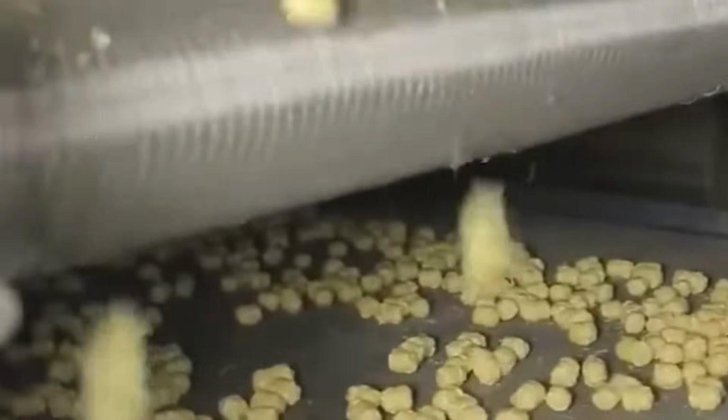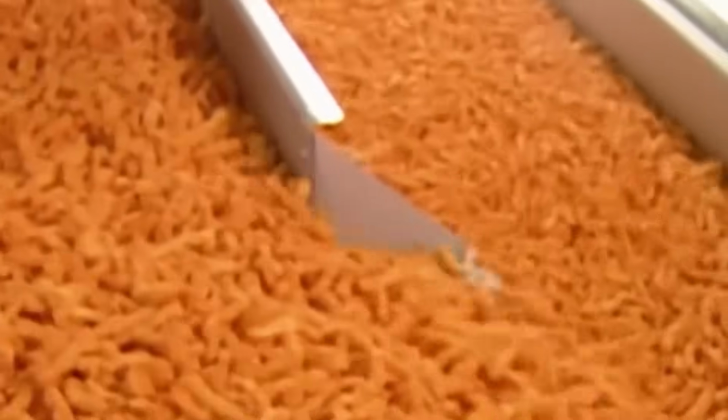The cornmeal is sifted through mesh screens to remove foreign particles, then passed through a dehumidifying chamber to achieve a standardized moisture content between 10.5 and 11.5% before entering the preconditioner. In the preconditioning chamber, dry cornmeal is mixed with water and steam under tightly regulated parameters. The purpose of preconditioning is to hydrate the meal to a target range of 18 to 20% moisture, while partially gelatinizing the starch to prepare it for the extrusion stage.